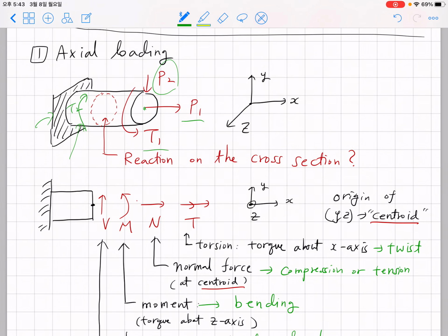And given this kind of forces, our textbook typically chooses this kind of coordinate system. For most problems you're gonna see in our textbook, the x direction will be the axis of this pillar, and y and z would indicate the cross-sectional area. Okay, so these are the directions that are parallel to the cross-sectional area. X will be the direction that's perpendicular to the cross-sectional area.